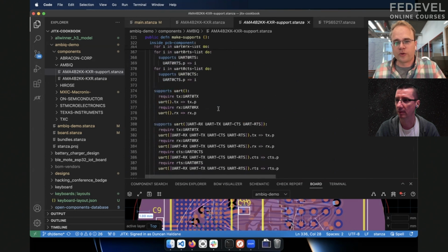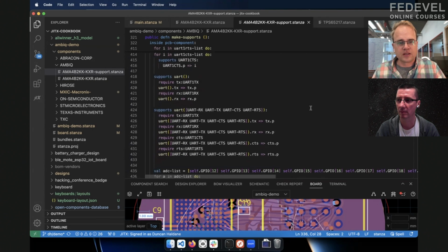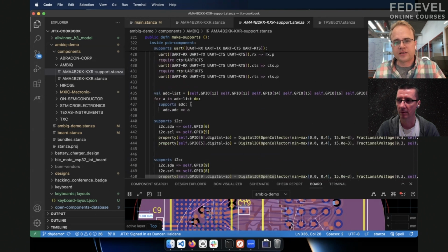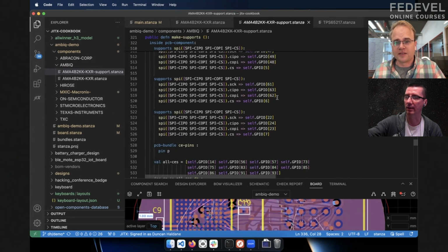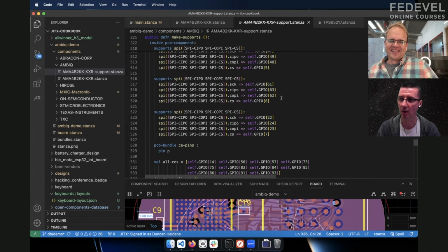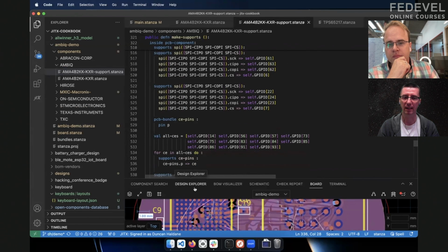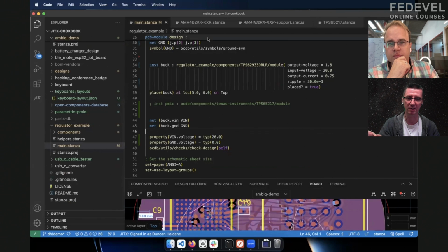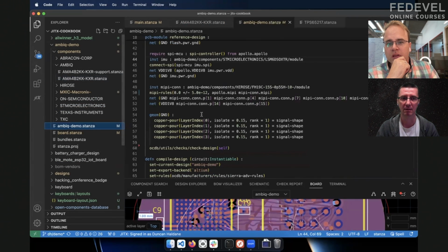And then you just load your entire pin assignment problem into it using this imported code. So ADCs, UARTs, I2Cs, SPIs. I see SPI, okay. So basically this is how it knows which of the pins is clock, which one is the MISO, MOSI, and chip select. Okay. And then you just tell it to connect the SPI from the processor with the SPI from the memory chip. That's it. Yeah, that's right.